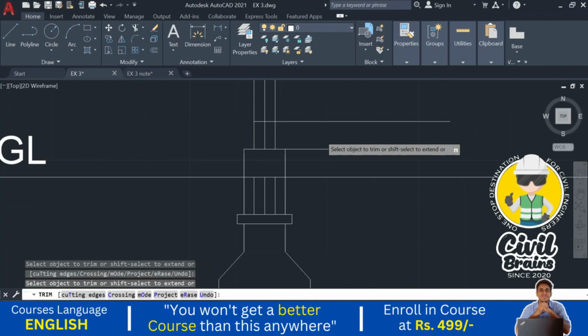One more thing, now we can consider the plinth beam, correct. So where do we need to provide the plinth beam here? We have provided the plinth beam wherever the walls are there. In the ground floor, wherever the main walls are there, above all the main walls we need to provide the plinth beam.